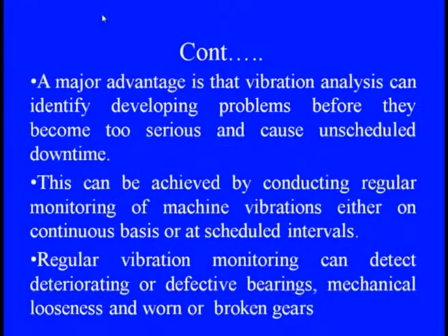With periodic maintenance, we always try to measure the level of vibration and the exciting frequencies, what kind of dedicated exciting frequencies are there in the spectrum, and what the vibration amplitude associated with each dedicated frequency is. We can easily figure out that mechanical vibration, whether measured on a continuous basis, meaning online fault diagnosis, or in periodic maintenance, clearly indicates the health of the system.